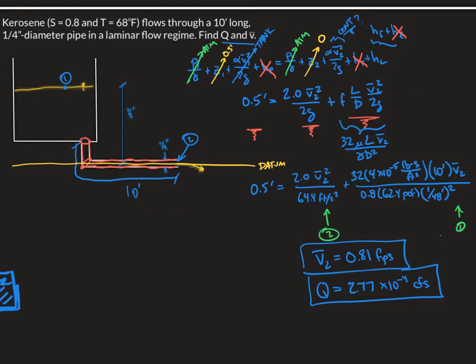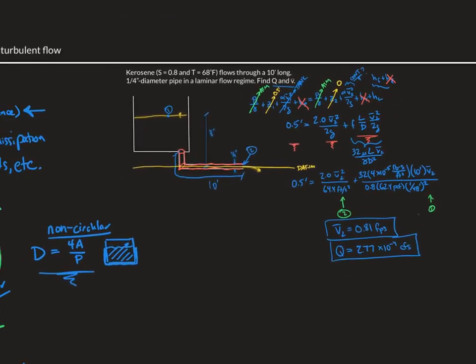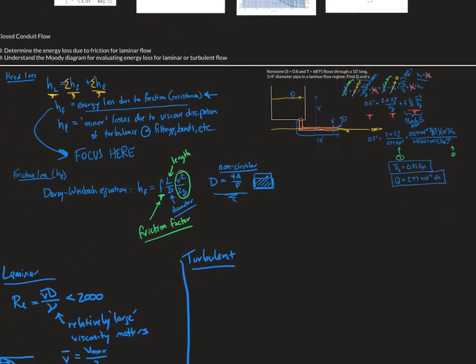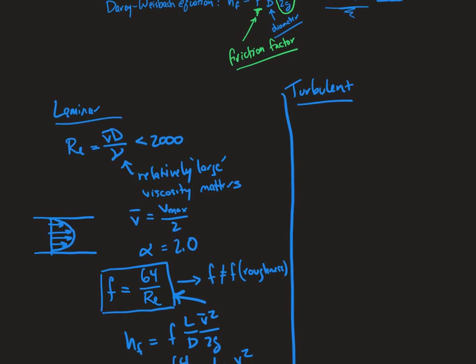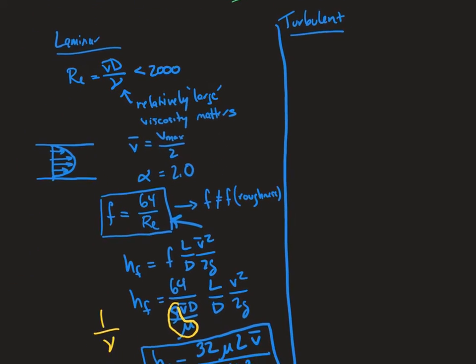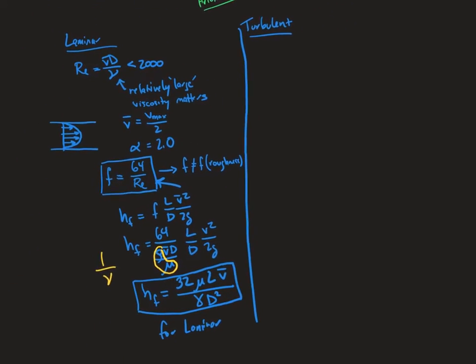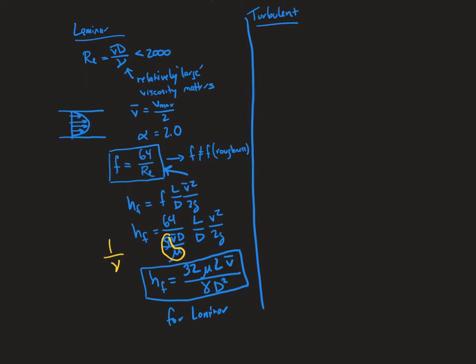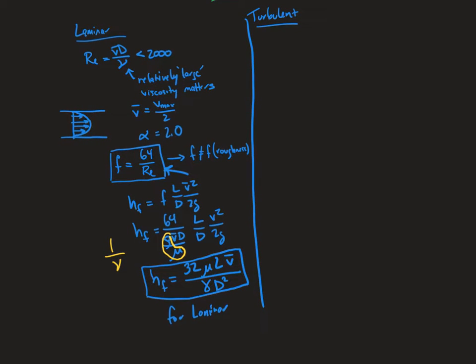Yeah, so let's zoom out and zoom back in over here and consider the turbulent case. Laminar, turbulent. In the turbulent regime, we will remember, kind of a throwback, the Reynolds number, same formula, is going to be greater than about 4,000 in a pipe.